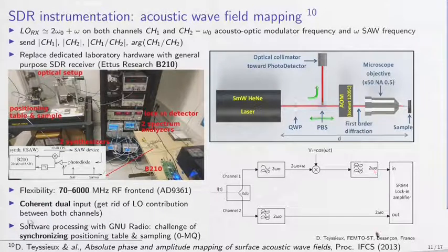So here we have a carrier frequency, which is the reflected intensity from the sample. The carrier frequency is simply the signal that went twice through the acousto-optic modulator without considering the vibration amplitude. This is representative only of the reflected intensity, reflectance of a signal. And then we have the signal that has been shifted by omega, the operating frequency of this device, and that is electrically shifted by another omega to bring it back to 2 omega 0.